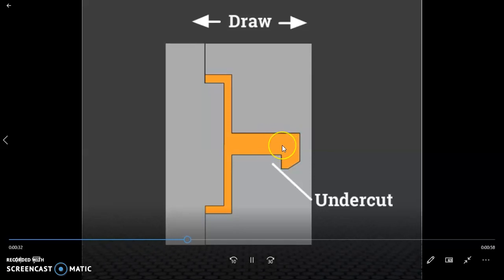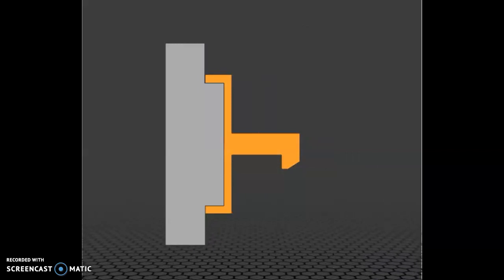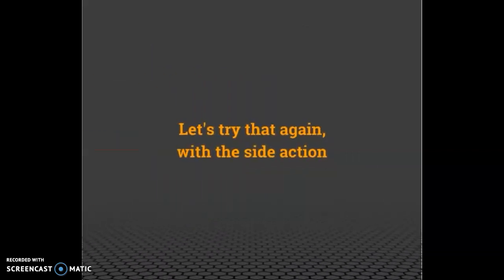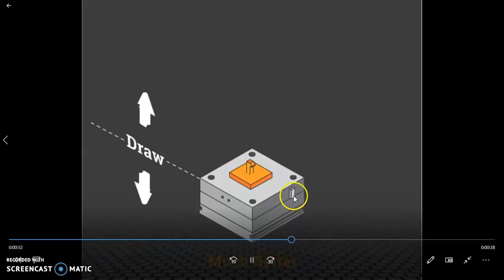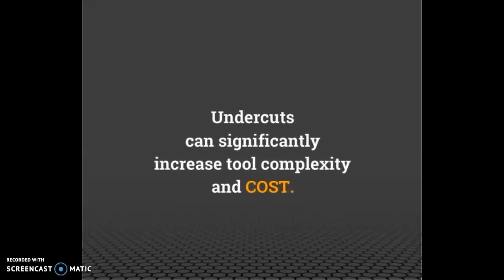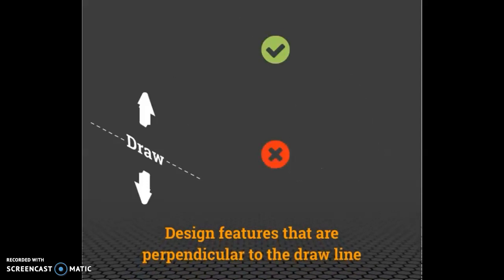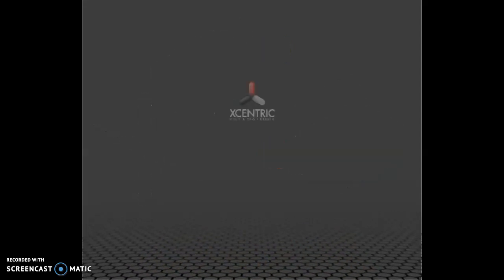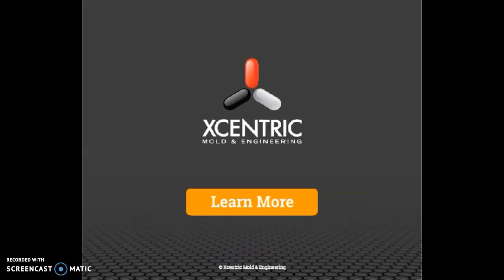Okay, this is undercut. Because undercut cannot strip from the mold, it needs an additional mechanism. This is the additional mechanism, which includes split core, collapsible core, split cavities, core pull, cams, cam pins, lifter or spring. The disadvantages of undercut are that it can add more cost, complexity and maintenance, as well as hidden costs.